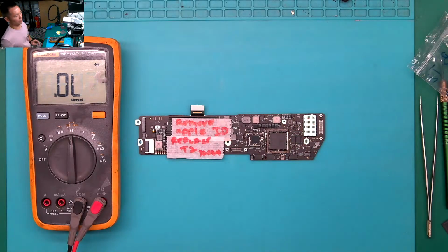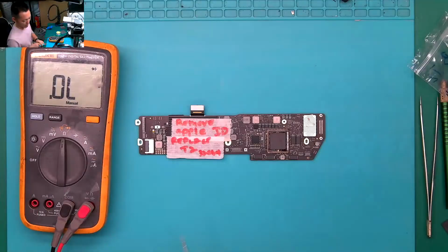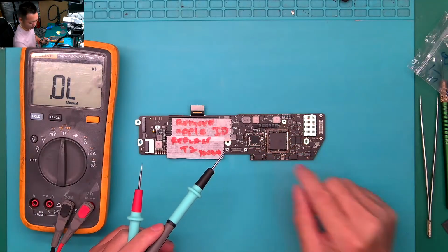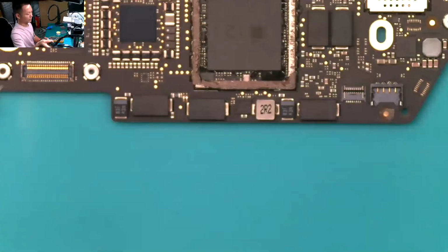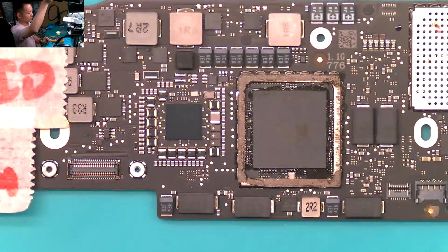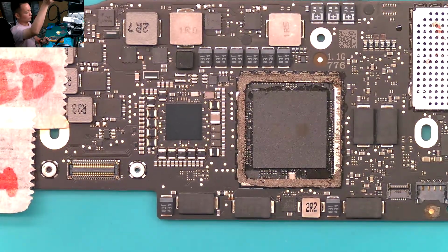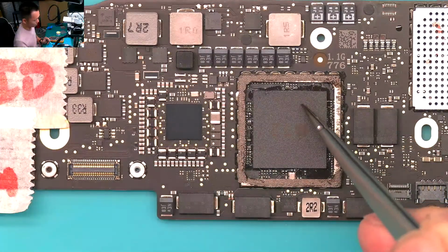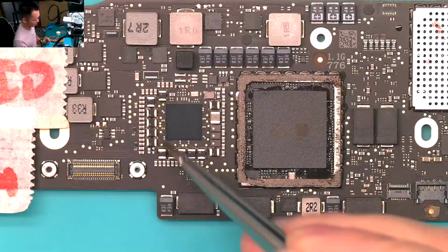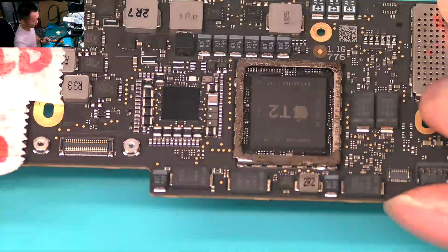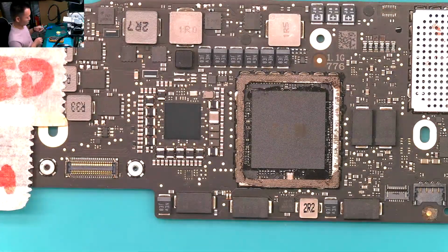Now you connect the power. Okay, you remember when you replace the T2 chip, then you must check around the PMUIC here. Around the PMUIC, all the inductors, because these inductors carry the T2 voltage. All the voltage is to the T2, so you must check all the inductors. Okay, no short, no 000. T2 is okay. Okay, now connect the power to restore.